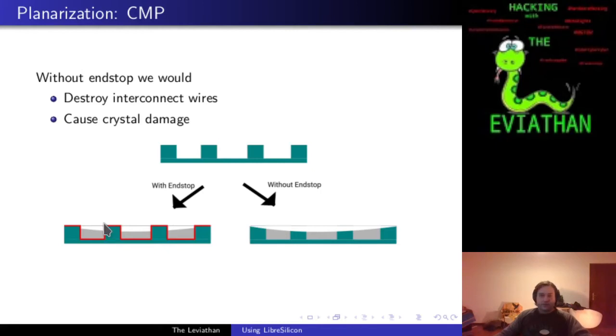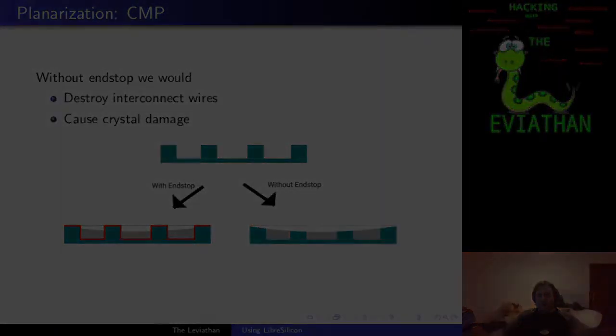Those edge effects exist always, but the bigger the wafer, the more even the distribution. This means with bigger wafers, you have a higher yield, because the area in which you polish away the exact right amount is higher the bigger the wafer. This is the reason why in the industry there is a push towards bigger and bigger substrate wafers.